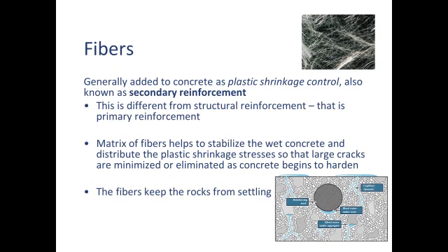That's Stokes' law, by the way. Big rocks settle faster, and as they do, they squeeze out all the fine sand. The sand acts like a filter, just like a pool filter uses sand to filter out the dirt in the pool water and the algae and whatnot. The big rocks squeeze everything together. The sand surrounding that acts as a filter, and the mixed water is squeezed out, and it forces its way out in all directions, and there are only two directions for it to go. The shortest paths are up toward the surface and down toward the subgrade.